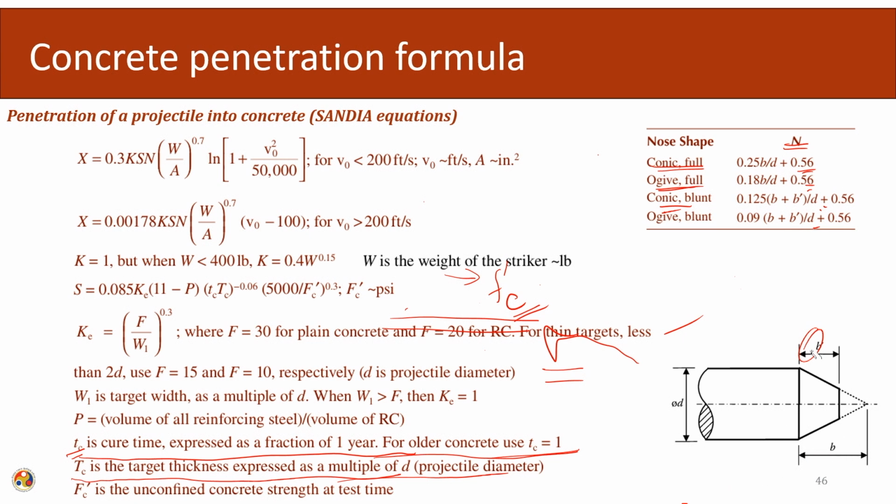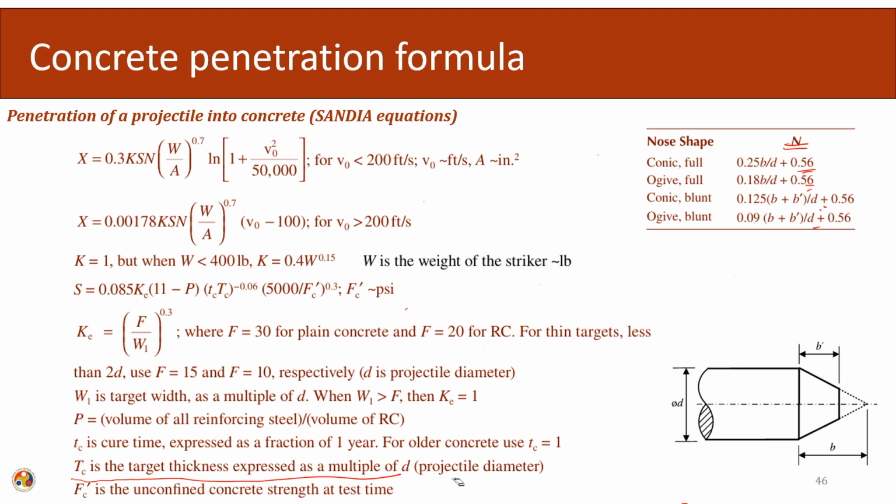Though the equation looks very cumbersome, the accuracy is higher because these are based on actual test data. The only problem with this type of equation is that they are only good in the range in which they were calibrated. If we come out of that range, the equation might not predict the actual penetration. So, care has to be taken when these equations are being used.